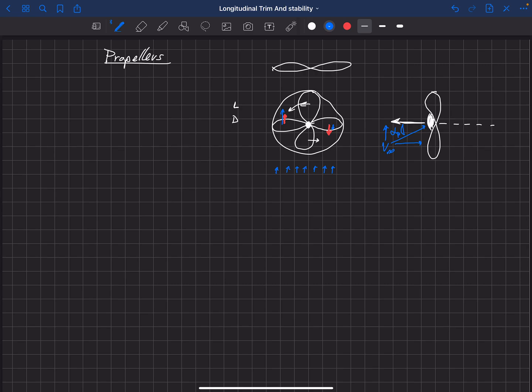Okay, so the net force in drag on this side of the propeller is going to be a net force in the upward direction that is new due to the angle of attack. And if we look at the drag on this side, it actually now has a net force as well in that direction. So both sides of this propeller create a net force upward from the force that it used to see, which was 0 if the free stream velocity were aligned with this axis. Okay, I hope that makes sense.